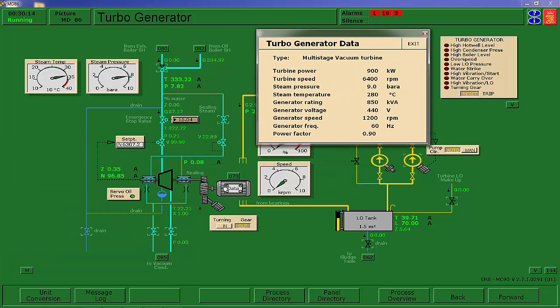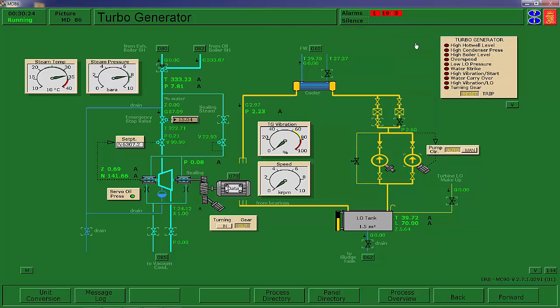running through a reduction gear. So your steam turbine runs through this reduction gear to run this 900 kW generator. Generators in startup have no real load. The only thing we're talking about here is the friction losses in the bearing and maybe some windage. It only takes about a horsepower to revolve this over. So the problem on opening up the throttle to bring it up is generally trying to just crack it barely open, or you'll overspeed this unit.